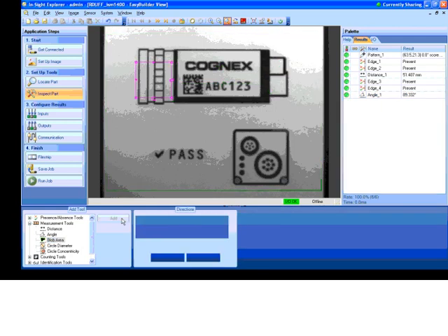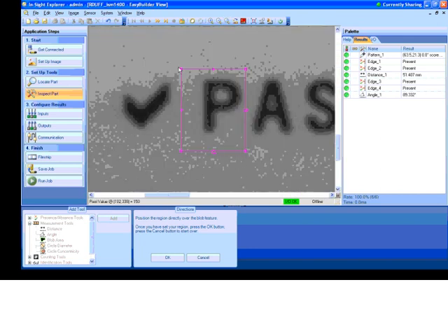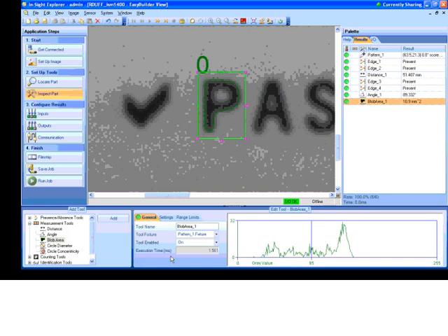Blob area is a little bit different. Click Add. I'm going to go down, let's consider this P, or blob. Right now I'm going to hold the control key, and you can watch the cursor change to a magnifier, so we can zoom in there. I'll define the P here. It's saying that the area of this particular blob is 10 millimeters squared. 10 millimeters by 10 millimeters. And you can see that it's defining the P here in light green.